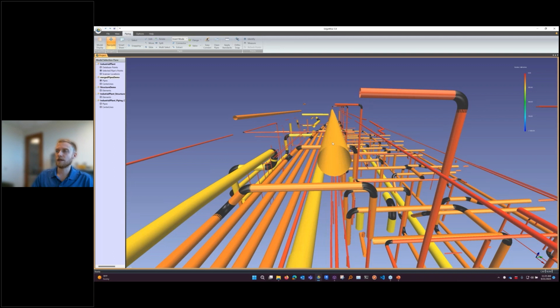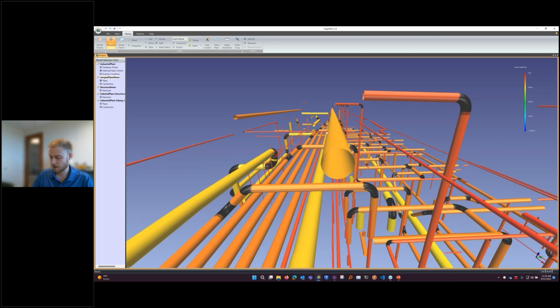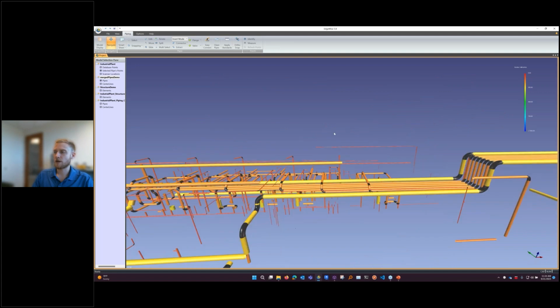And so this is a great little example where we are making a pipe run that follows the point cloud. This is not a straight line. This is just what's happening in the real world, and we're representing that natively through our workflow. That's the default, that as-built condition. We can change that. We can make it a straight line if we want to, but the default is going through and fitting into the point cloud. So at this point, we've got a lot of our model done here.